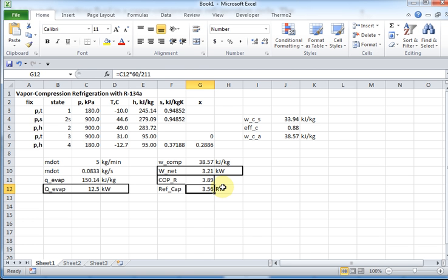Now, if you have a very new home that's tight, not a lot of leakage, and you have very good insulation in the walls, ceilings, roof, and all that, then that ratio drops. You don't need such a big air conditioner to be comfortable. But that's a good rule of thumb: for every 500 square foot, 1 refrigerant ton.